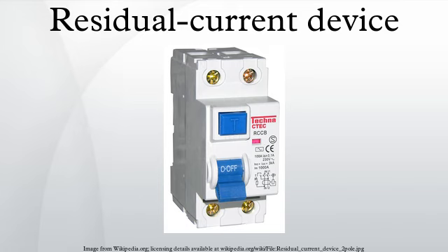Some early RCDs were entirely electromechanical and relied on finely balanced sprung over-center mechanisms driven directly from the current transformer. As these are hard to manufacture to the required accuracy, and prone to drift in sensitivity both from pivot wear and lubricant dry out, the electronically amplified type with a more robust solenoid, as illustrated, are now dominant.